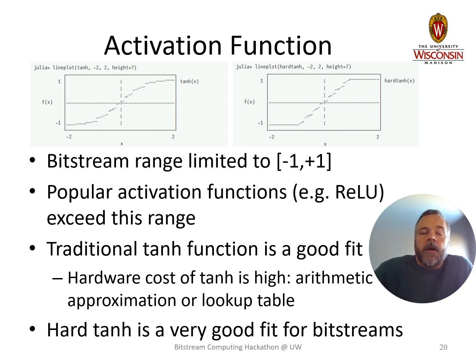However, the cost of implementing a nonlinear function like tanh is quite high. We either have to use some complex arithmetic to approximate it, or we have to use a lookup table. However, there's another substitute activation function that works quite well, called hard tanh, or a piecewise linear tanh. Shown on the top right here, the plot illustrates that in the active range it's a linear function, and outside the active range it just saturates at +1 and -1.